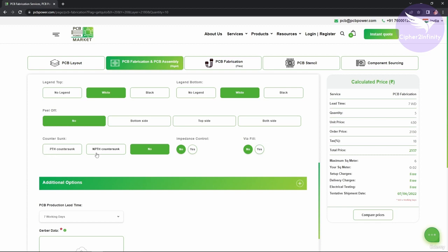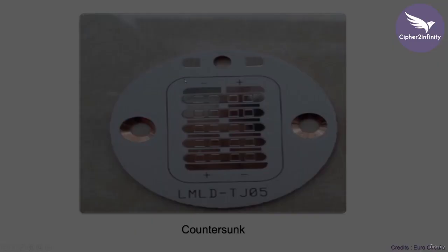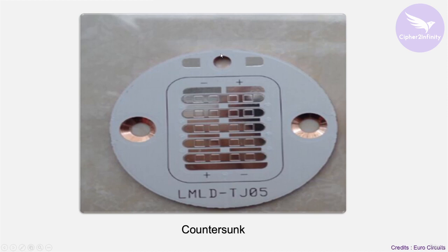And mounting hole is actually an example of NPTH. So let me show you how exactly the countersunk looks like. Now in this image you can see here, you just observe this hole, okay? So there is actually no countersunk around this hole. So here in this case there is actually countersunk. So when you have the countersunk on your PCB, the head of the screw will be properly fitted on the PCB, okay? And it will not come above the PCB. So that's basically the main purpose of countersunk.